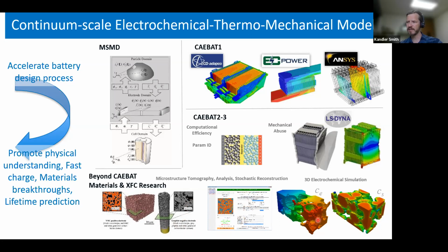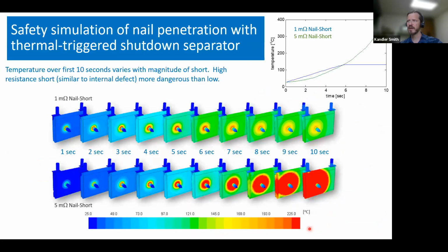Today's lithium-ion systems have only about 5–10% expansion contraction in the materials with charge-discharge processes. Some future materials like silicon have 300% expansion contraction. So we're also presently building in mechanics and large deformation processes into these models. So these 3D models are very effective for simulating safety events and are really good for connecting things that you might run in the laboratory, that type of test data, with a field defect, which might have a different magnitude of short.